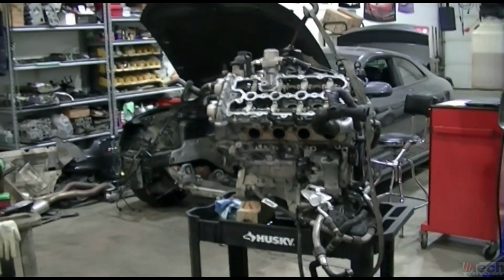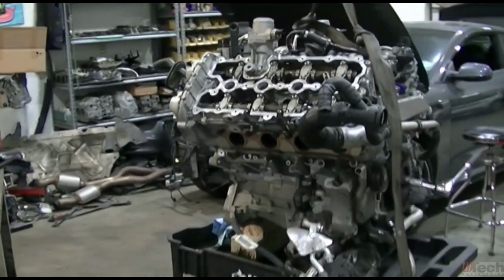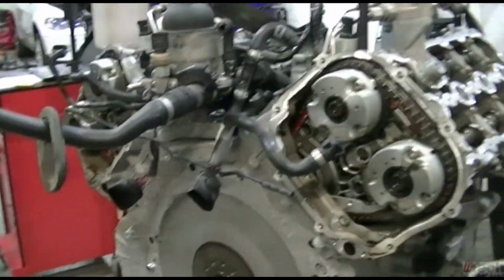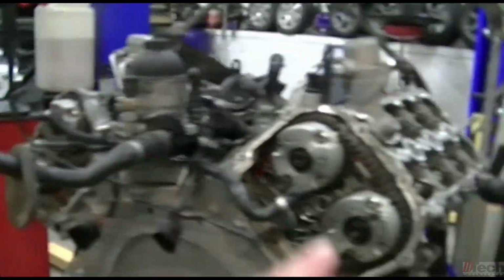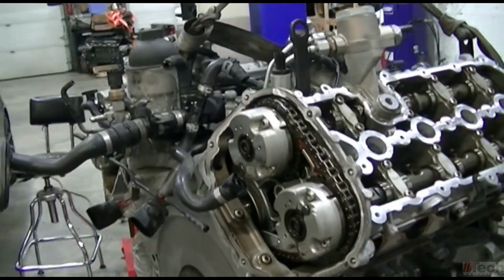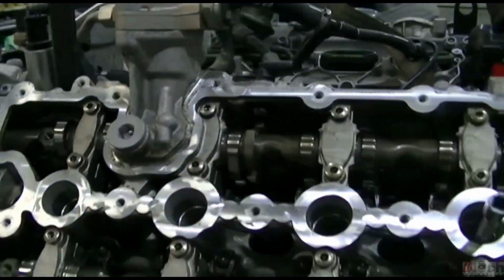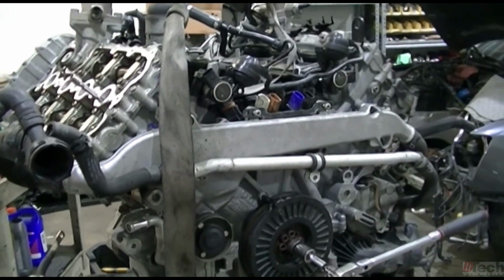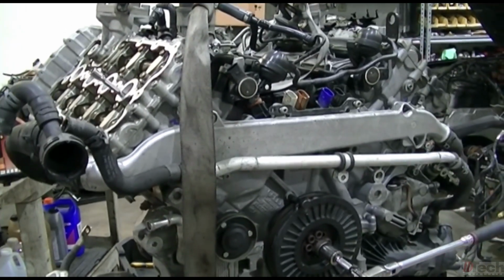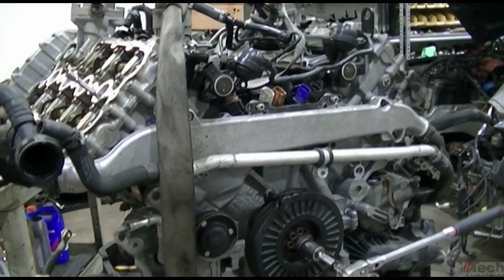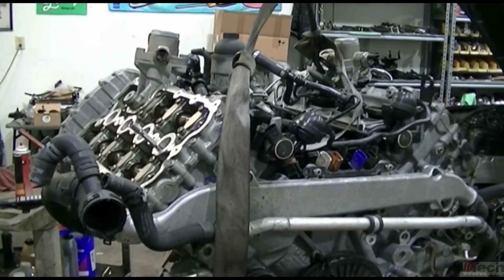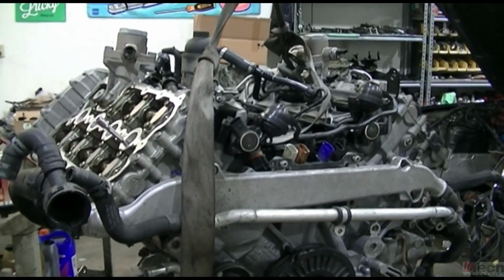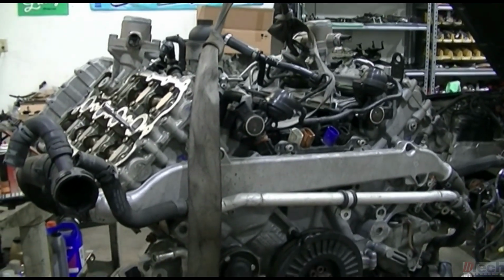Alright, as you can tell by the obvious, we've got the engine removed from the vehicle, and I've got the upper timing covers removed, got valve covers removed, and I'm going about just setting it at the timing checking point or setting point. And before I take anything apart, I just wanted to see where the cams and everything are lined up, just to get a better idea of physically seeing compared to the scope capture.